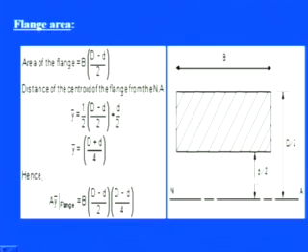So if you want to calculate the distance from this neutral axis to the centroid, first d by 2, plus you see here half of this distance. So if we manipulate those things, we have y bar equals D plus d by 4, and then we can calculate the area A y bar for the flange, because this is the main dimensional parameter for calculating the shear stresses for different sections.